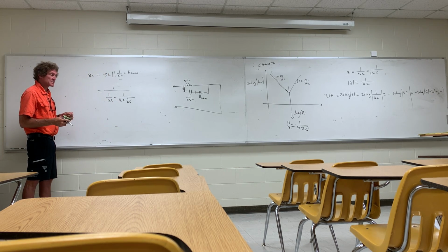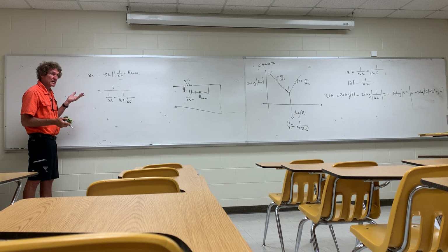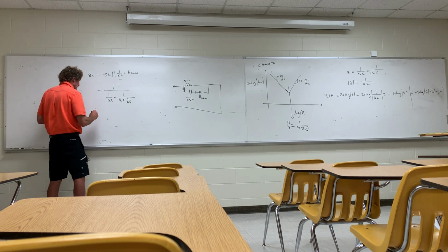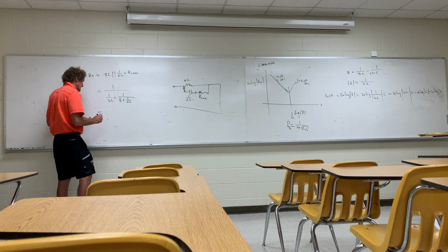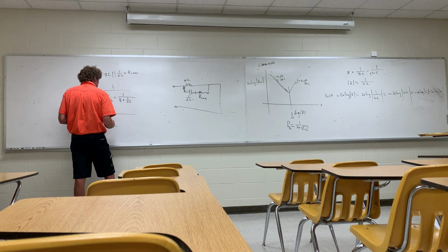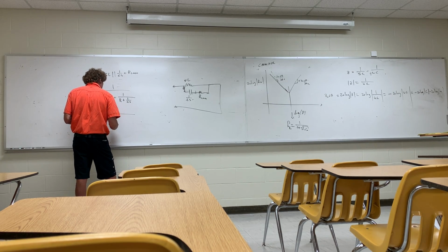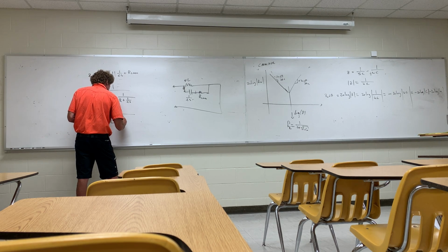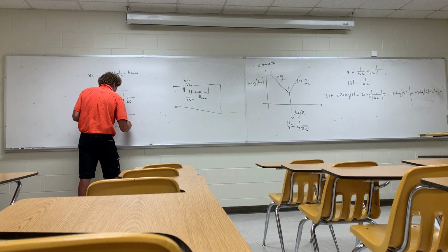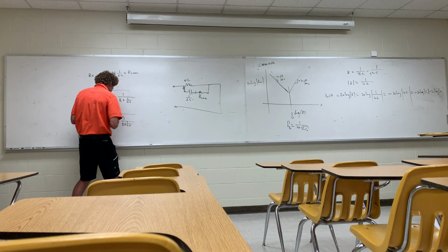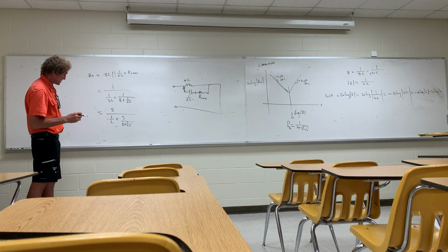Now the fun begins. I just want to get something where I have a numerator and a denominator that are polynomials. So I'm going to start by multiplying everything top and bottom by S, and I get S. Then I get 1 over L plus S over R plus 1 over CS as such.